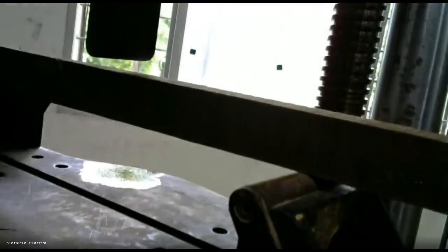Again the loading criteria: that is our simply supported beam, with a point load acting at center. Then we can directly calculate our bending stress value according to the bending formula, M by I equals sigma by y. And according to that we have to check the bending stress value, whether that beam cracks at the bottom side or top side.